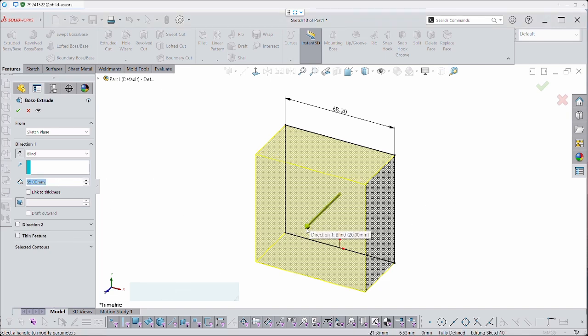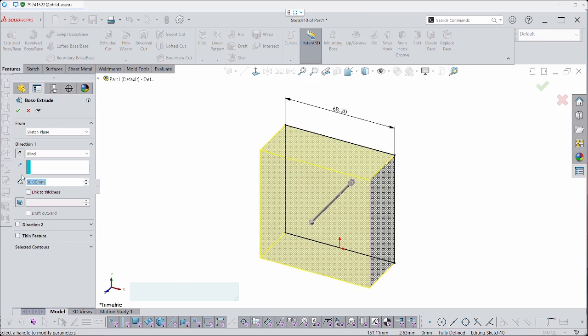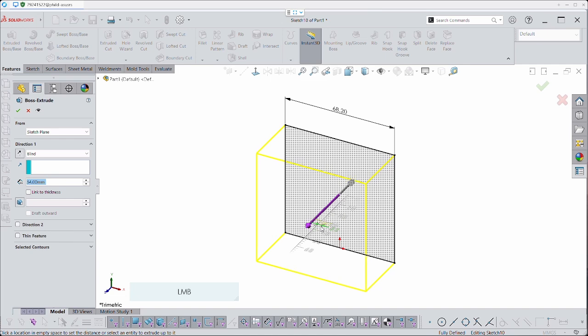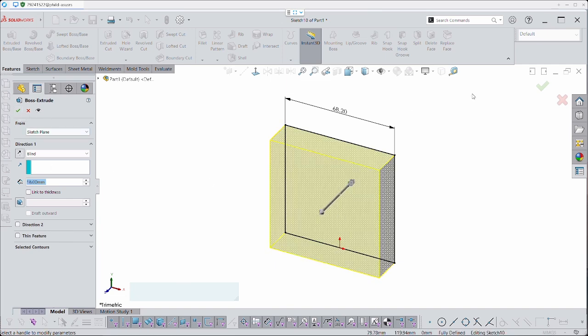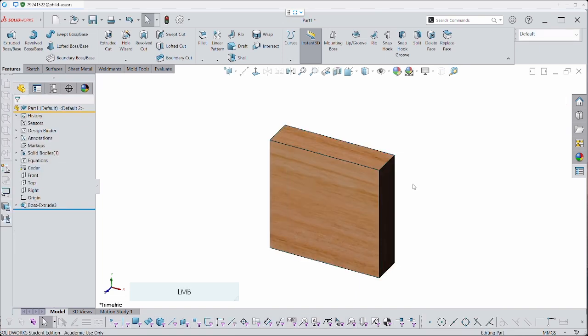And the other way you can do this is you can grab this button here and you can drag your face in or out to whatever you want. Now just have a look in the left hand side how that changes. So if you can't see what's happening on screen, just have a look to the left in the properties manager and you'll see what dimension you're getting exactly. You can even get to some sort of odd dimension, like 18, and then you can exit either by going to that button there or that button there, or hitting the enter button, or right clicking and hitting OK.